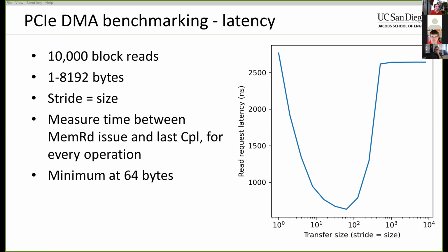So this is also one of the motivators behind the variable length descriptor support, because right now Corundum reads all the descriptors individually and they're 16 bytes. So I guess you have 4 of those inside of each 64 byte block. So you read that 4 times and you're going to suffer that multiple read penalty that we're seeing here.